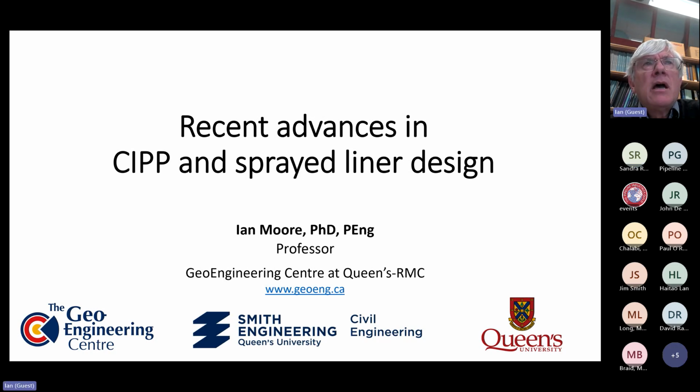Okay. So what I've been presenting this afternoon allows you, if you know what the kinematics, what the motion at those joints, at those ring fractures are going to be, to make an estimate of what the local stress and strain will be in the liner.